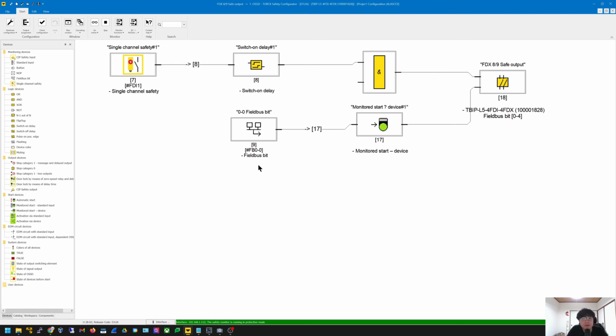So finally, I show here the field bus. I show a little bit more in here, and then I will try to show you the result. And double here, you see FP00. It means byte 0 bit 0 of the Ethernet IP connections. Okay, it's output. And here is the input address of 01.